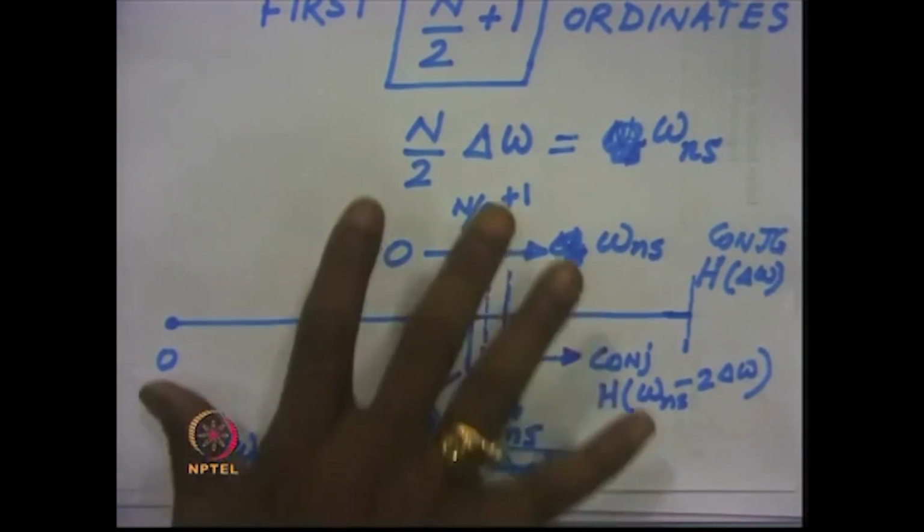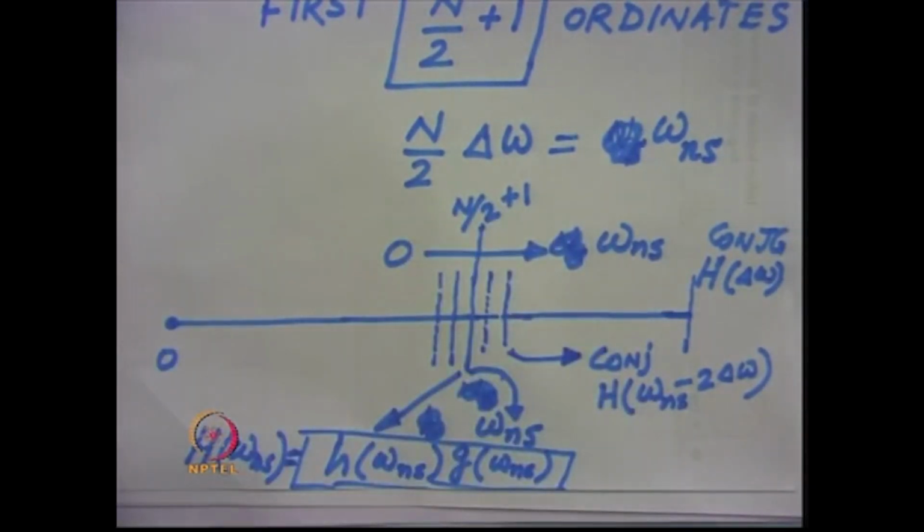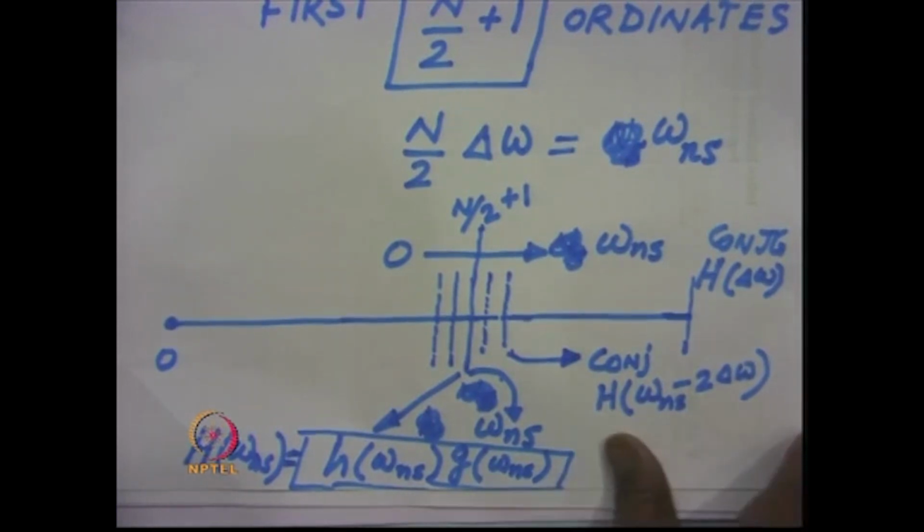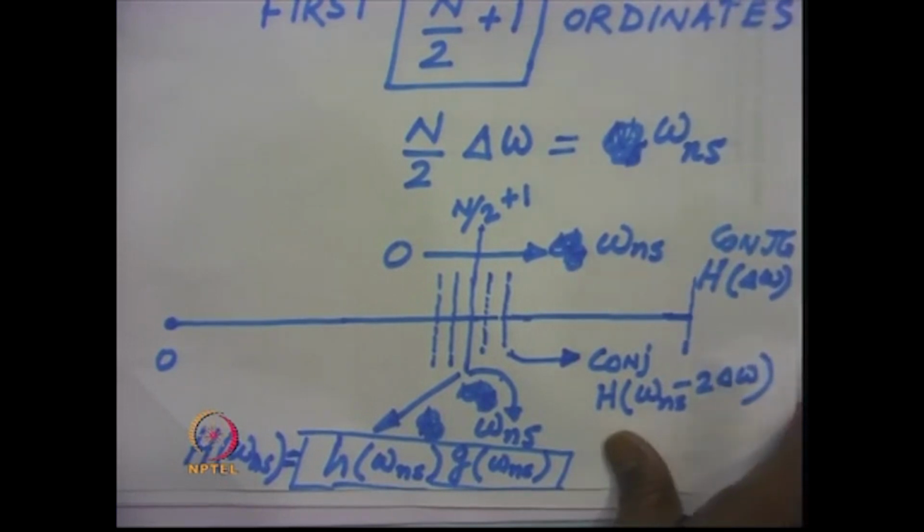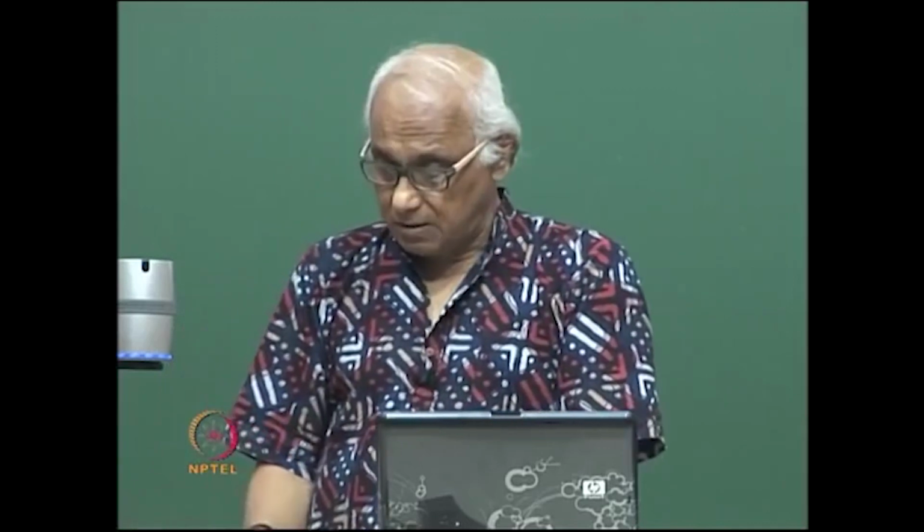Now, once we give these 32 complex numbers, that means on this side we have complex conjugate numbers, then the IFFT would give us the response of the single degree of freedom system to the specified ground excitation xg(t). xg(t) is the ground motion.